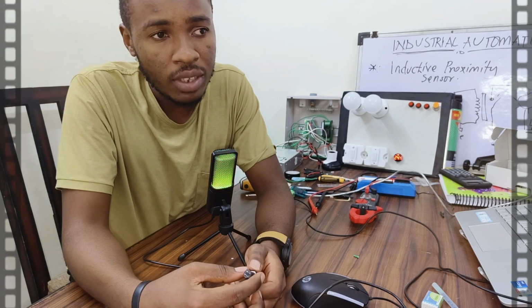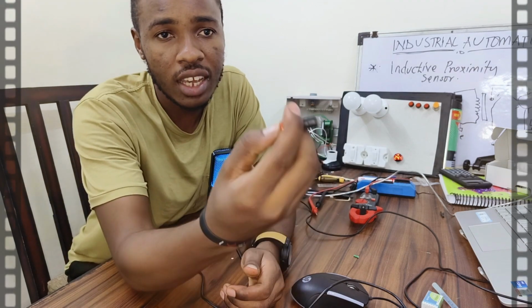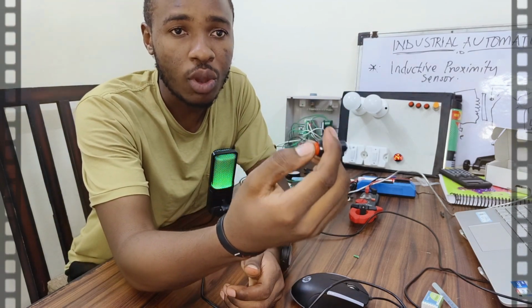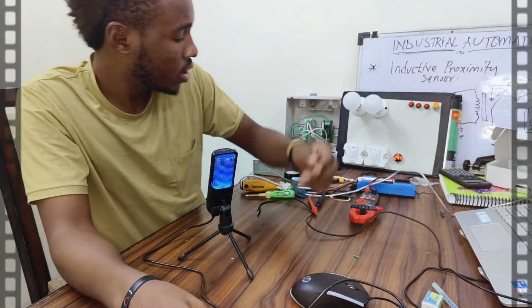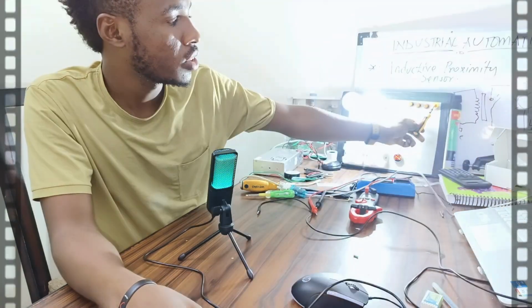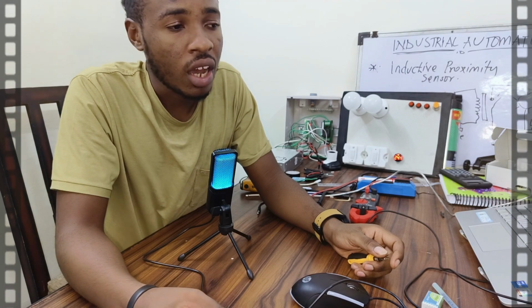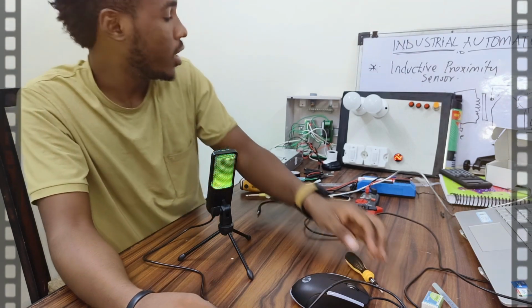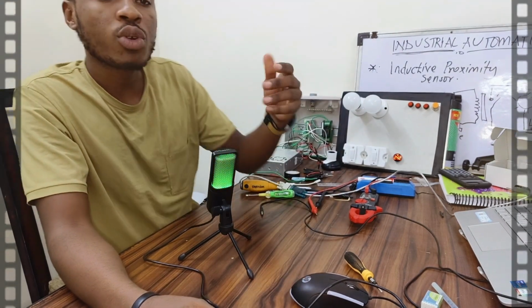So what types of switches? We have mechanical switches. This is a mechanical switch because you can hear its clicking sound; I have to mechanically click it. And then we have a sensor switch. This is a sensor switch; it has sensed a ferromagnetic material. And then we have the electromagnetic switch. An electromagnetic switch is a relay. A relay is here. For a relay, I have to command it using a particular signal, a voltage signal.